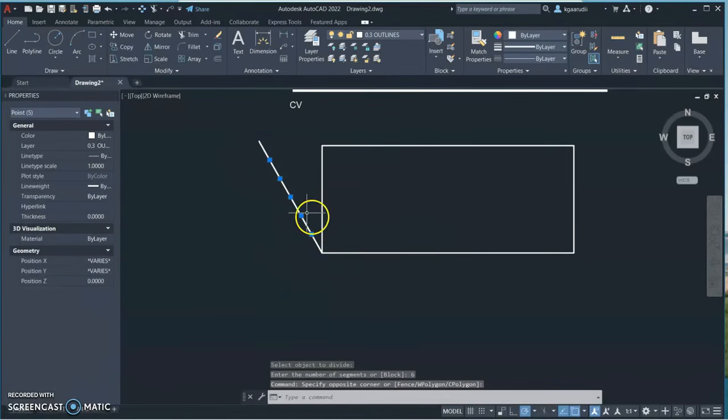So if you are using a drawing board, since this line is 60 millimeters, we are going to divide this line by 10. So we are going to have 6 spaces, and the distance between those points is 10 millimeters, 10 millimeters, 10 millimeters. Why are we doing the divisions on this line instead of doing it straight here? It's because we are using 50, and if you say 60 divided by 6, we are going to get 8.333. So it's kind of impossible to measure